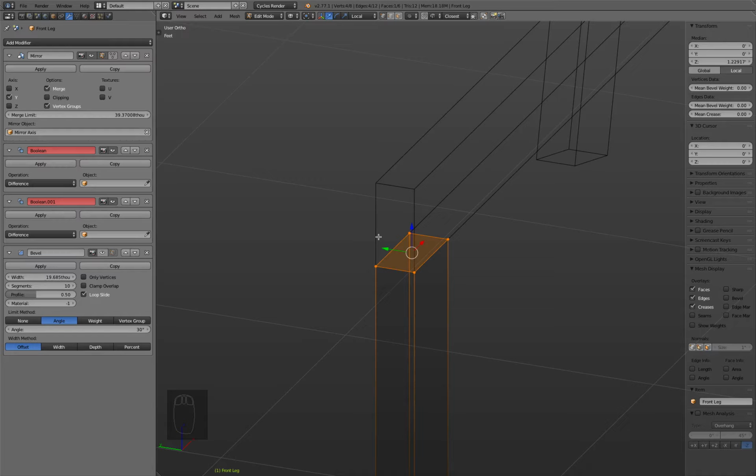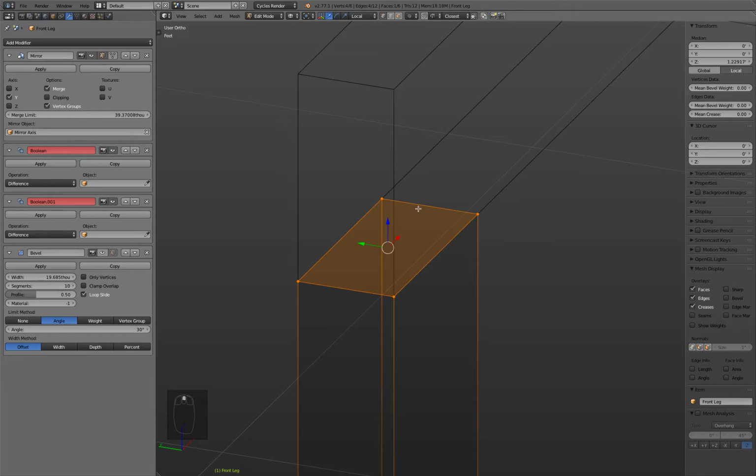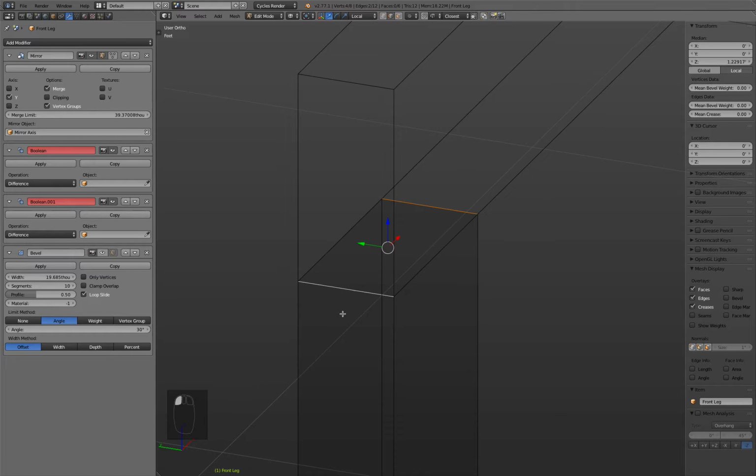So we want actually to recreate the same joint. In Fusion, when this would be an extrusion, I would create a new sketch on this face that is selected, and then I draw a midline. And we're going to do exactly the same. But while in Fusion we add a sketch to extrude something, in Blender we slice the geometry, so we have a new set of vertices we can extrude. We only need a line between this edge and this edge, slicing that face.